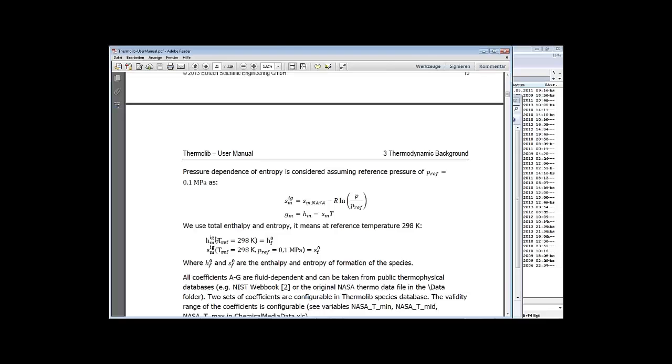The question is only what the output temperatures will be and what corresponds to the different concentrations. So the enthalpy of combustion is inherently included in this formulation. You don't have to explicitly give any enthalpy of combustion of any fuel, be it dodecane, coal, methane, whatever. That's already done by the basic thermodynamics by using the absolute enthalpy, including the chemical energy as well.